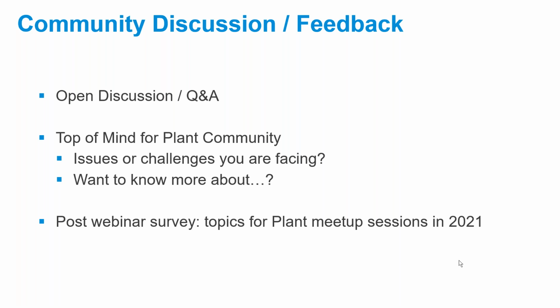Yeah, I think we could definitely get some known issues that we've experienced, either from support cases and things of that nature. I've run into cases where you have pipelines that are hundreds of feet long, and it just has trouble running all that out, and you have to split it up a bit and put some breakpoints in there. There are workarounds for things like that. It's just knowing what to do to make sure that what's going into the ISO engine will produce a cleaner output in the drawings.